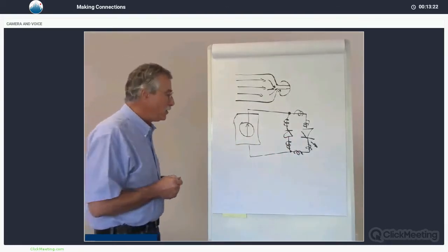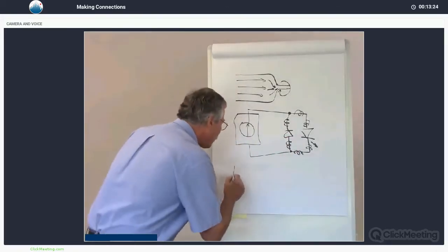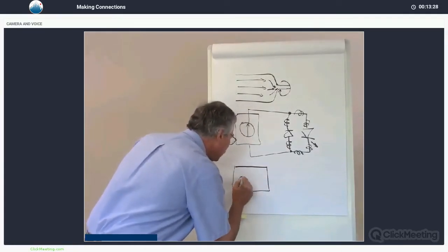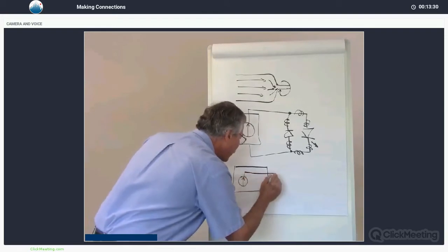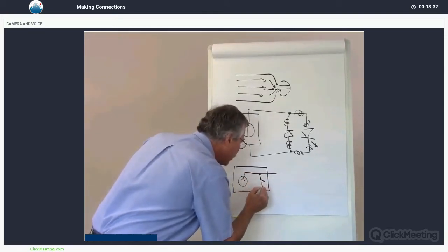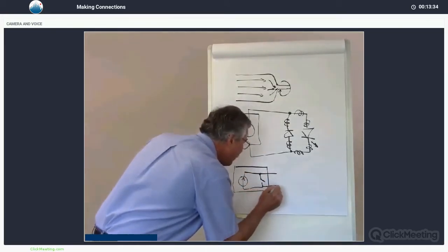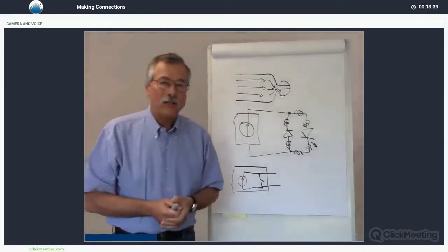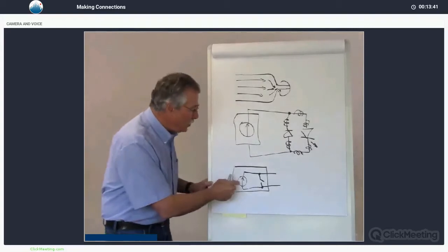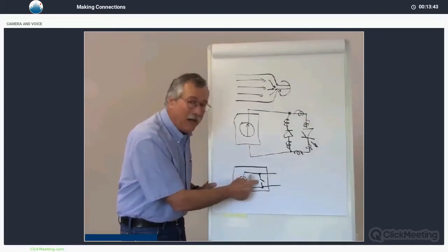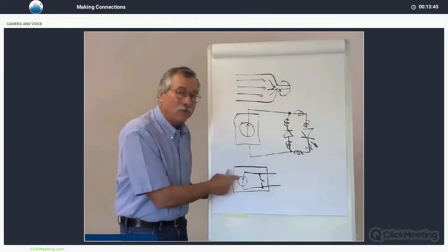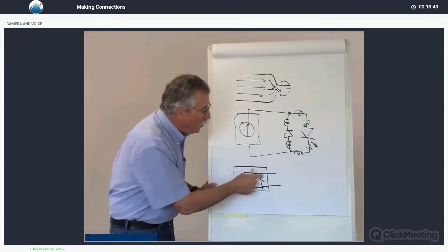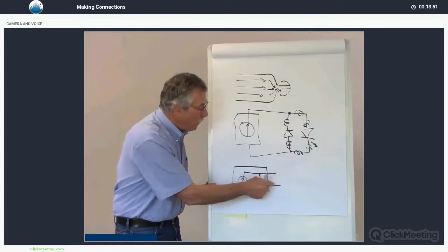Here's another thing to consider, and you'll see an example of this later. Our driver sometimes consists of a current source and a switch. The switch is what's actually creating the pulses. We've got a current source, and while the switch is on, we've shorted the current source out, which does not harm it. A current source can drive a short circuit just fine. We have no pulse at this point.